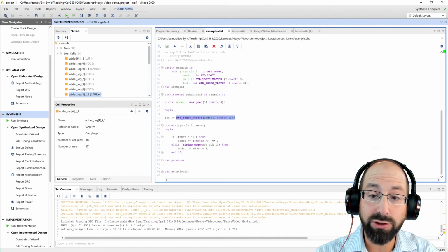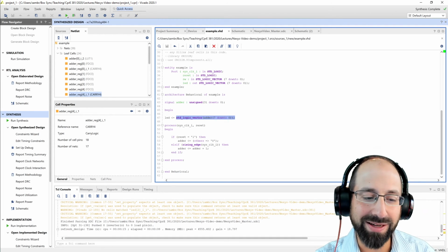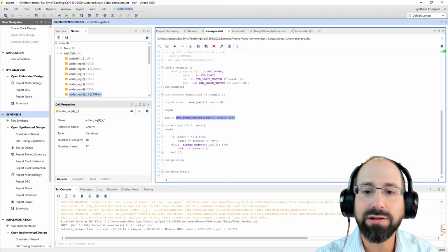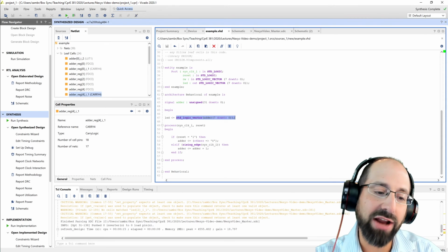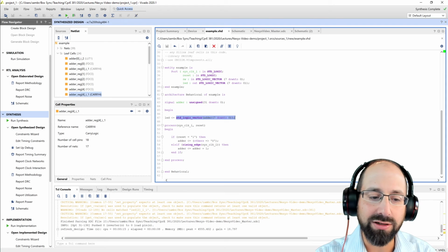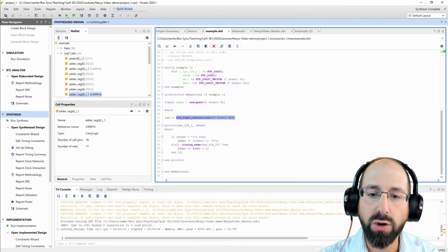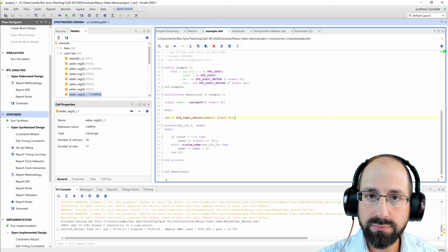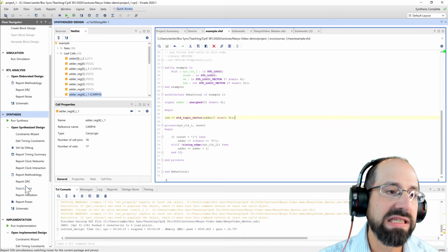Just use your adder, just use your ALU and hard code it to be plus 4. The tools will figure out the rest. The synthesis tools certainly will figure out the rest and will determine what parts of that logic are actually needed for that plus 4 operation, and let's remove the rest of it. And there's quite a bit you can get rid of when you know it's adding a constant. And if you're not using all of your bits of representation, it can remove all of those as well.